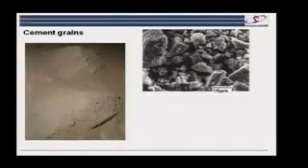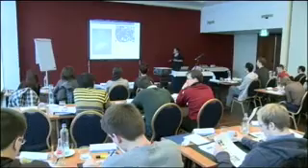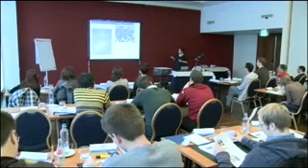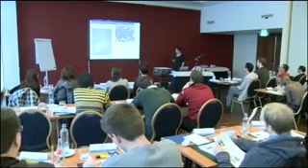We see also that the grains tend to be agglomerated together. This is true of any powder. When you grind something up, you generate a lot of static electricity, which tends to hold things together. It's like dust, which forms great mounds in your house if you don't do the vacuuming every day. So this is the cement grains, and sometimes we can see that we've got small gypsum crystals on the surfaces.